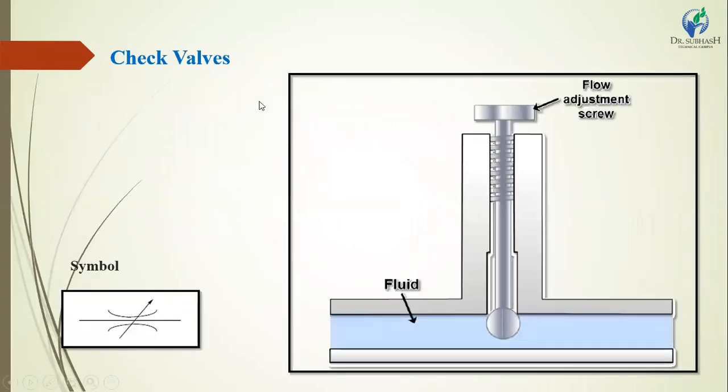Here is the normal valve, a simple flow control valve. First I will say how many types of flow control valve are available: fixed restriction FCV, FCV with reverse free flow, temperature compensated FCV, pressure compensated FCV, and both pressure and temperature compensated FCV.